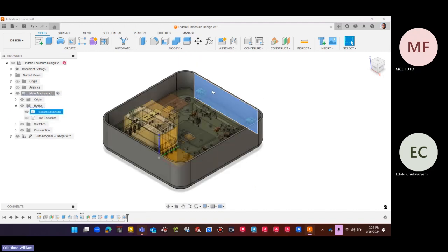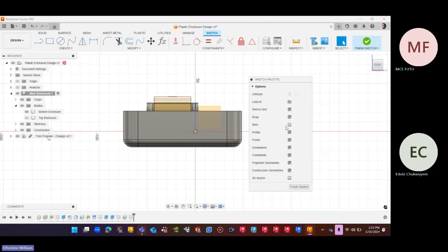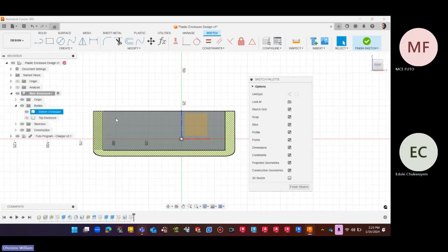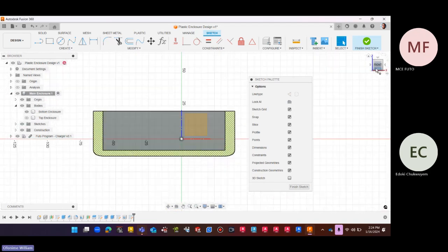So you just click on this point, right-click, and create a new sketch. We can't see what's happening there. So we come to the sketch palette, you see Slice, you click on Slice. Right, all that's understood. So you could actually see what's happening within this environment. Understand? So what are we basically trying to do?